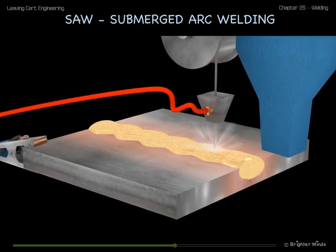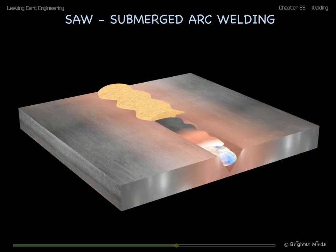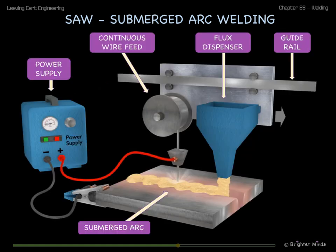As the weld joint cools, a slag layer forms on the surface. Unused powdered flux is hoovered up and can be used again. Submerged arc welding is suitable for long, straight welds. The dangerous arc light and fumes are reduced because of the submerged arc.